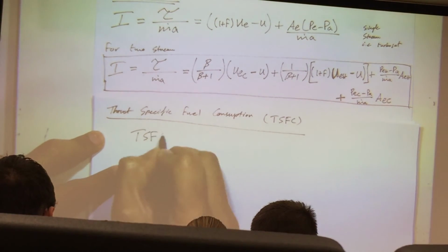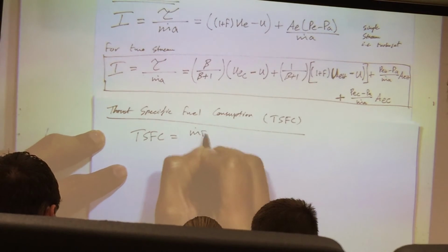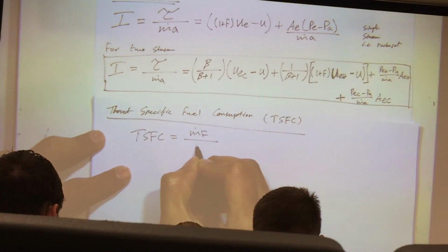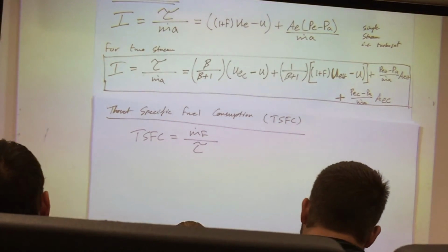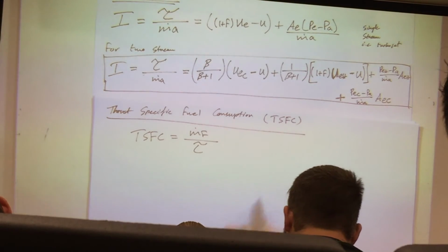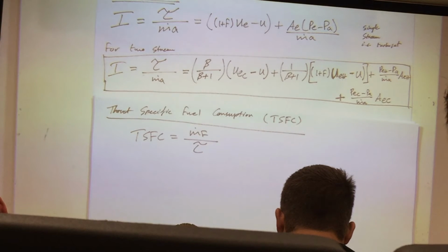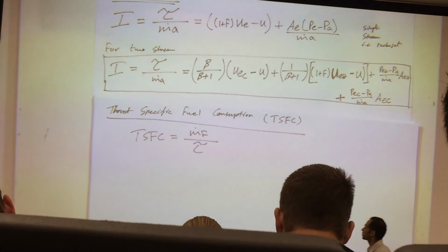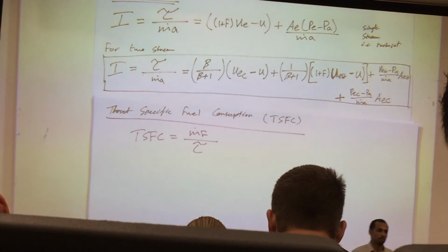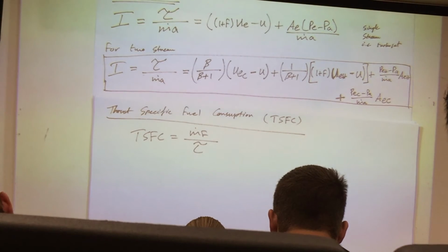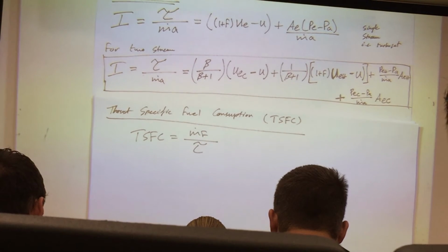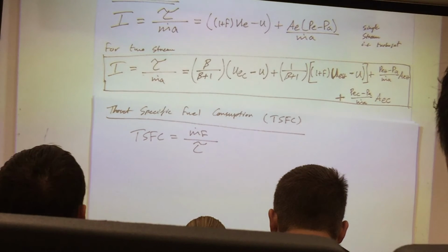So what is TSFC? TSFC is equal to how much fuel I'm dumping into the engine relative to thrust. Very simple, straightforward equation. Now, what do we want to do in general, whether we're military engines or commercial engines? Do we want to increase that value or decrease it? Decrease. Just how much fuel I'm putting in relative to the thrust I'm producing out of that engine.